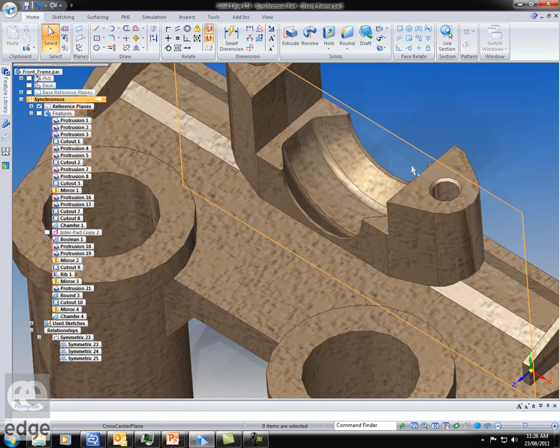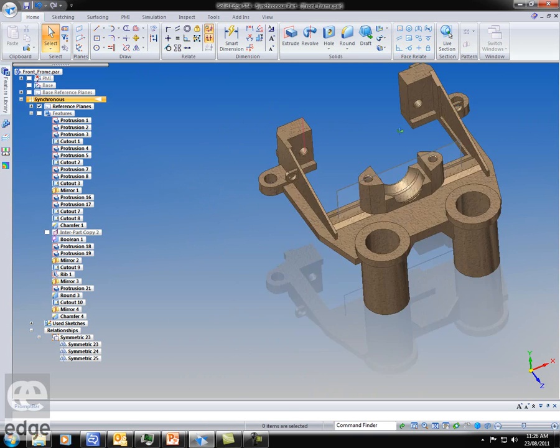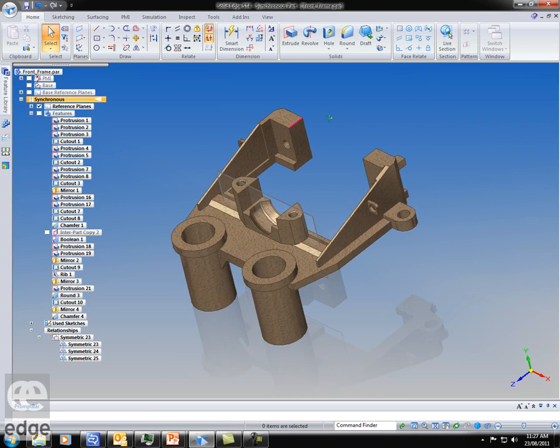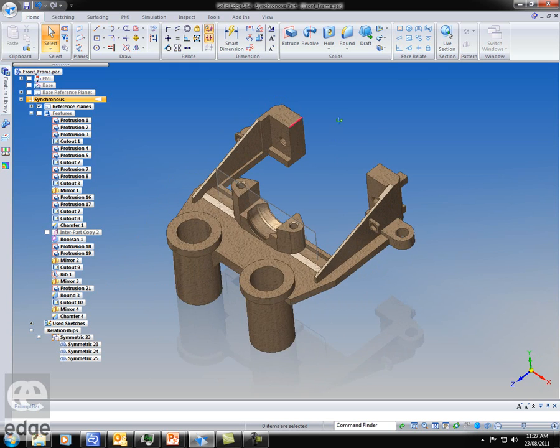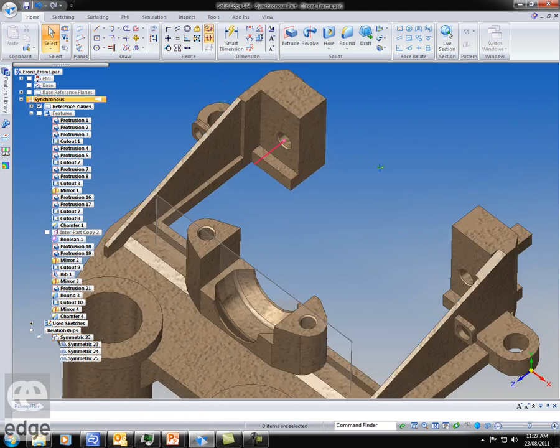If I zoom in on that, my middle mouse button, if I double click, now will fit automatically. And if I click once on my middle mouse button, then select an edge, that's the edge I'm going to rotate around. So when I hold my middle mouse button again to rotate, it's that edge. If I click again with my middle mouse button, select the edge, and hold down the middle mouse button again to rotate, it's that edge that'll rotate around. If I click once, pick the circle, now when I rotate, I'm picking the center of the circle to rotate around.